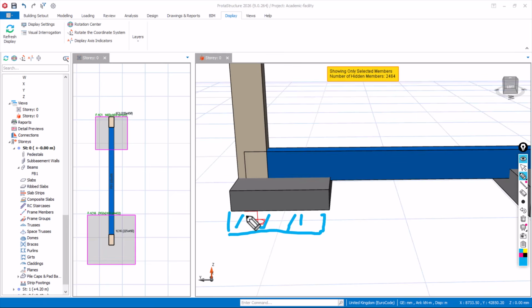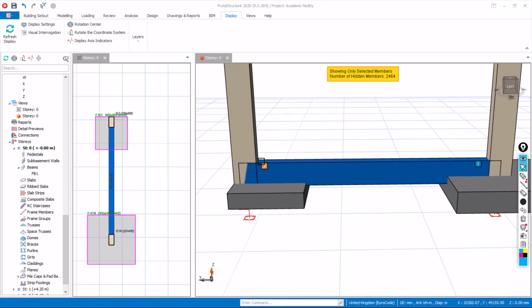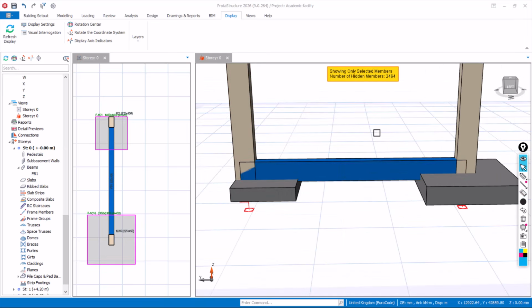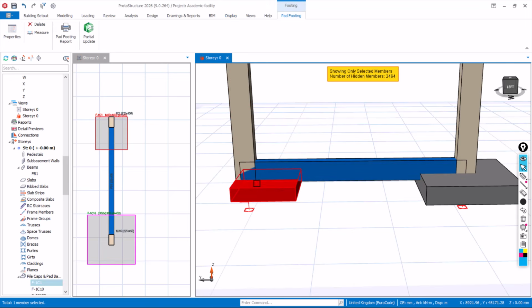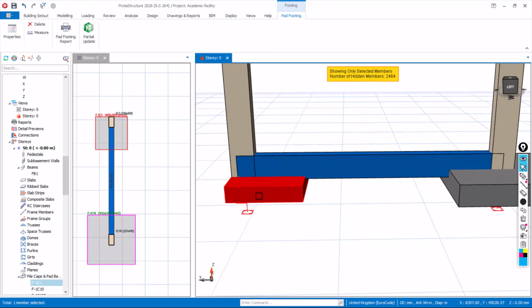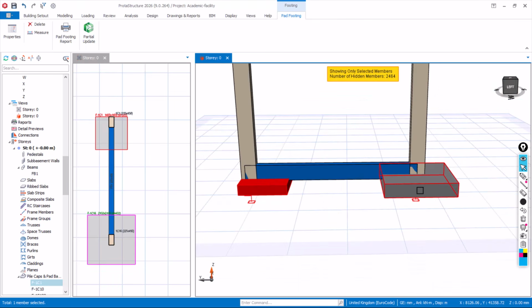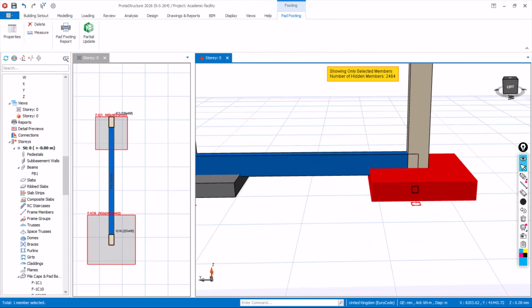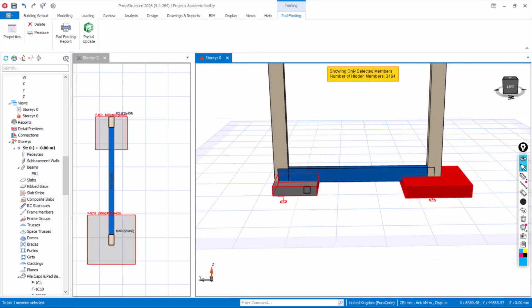Okay, that is fine. So in this course, once you have modeled it, what is the next thing to do? The first thing is to model it correctly, right? Once you have modeled it correctly, it then moves to design. Now note that this footing here must be doubly reinforced. It's a must. For another footing, you can choose not to apply double reinforcement; if you apply it, maybe you're just wasting money. Single reinforced is okay for that. But for this one it is a must that it must be doubly reinforced.